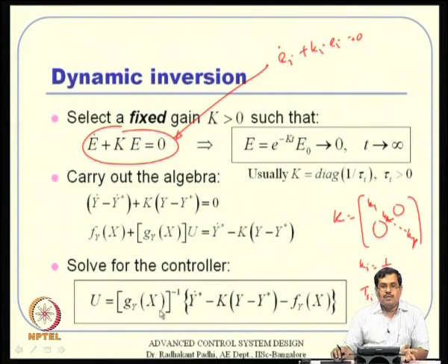I mean, there are practical problems, as we all know. For example, this control that you compute can go out of bound. If it is out of bound and you just cannot implement it, this formula is no more valid. So, obviously, at that point of time this dynamics is no more valid. Similarly, if it violates a rate constraint or something, then also this dynamics is not valid. So, there are several issues that will pop up here.